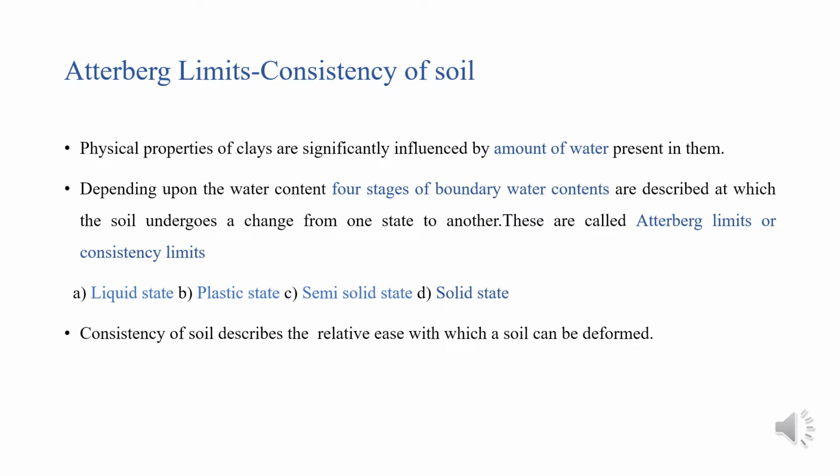At these water contents, the soil undergoes a change from one state to another. These boundary water contents are called the Atterberg limits, or the consistency limits. These 4 stages are the liquid state, the plastic state, the semi-solid and the solid state.